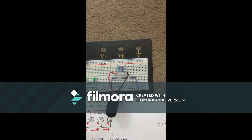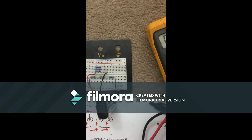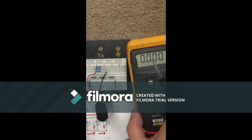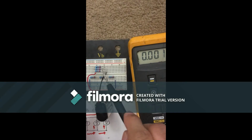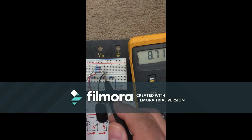Okay, and then let's test. We should be getting a reading that's almost or close to 9 volts for each of the resistors that we have. For the first one, we have 8.7 volts. Second one, we also have 8.69. The last one is 8.6.